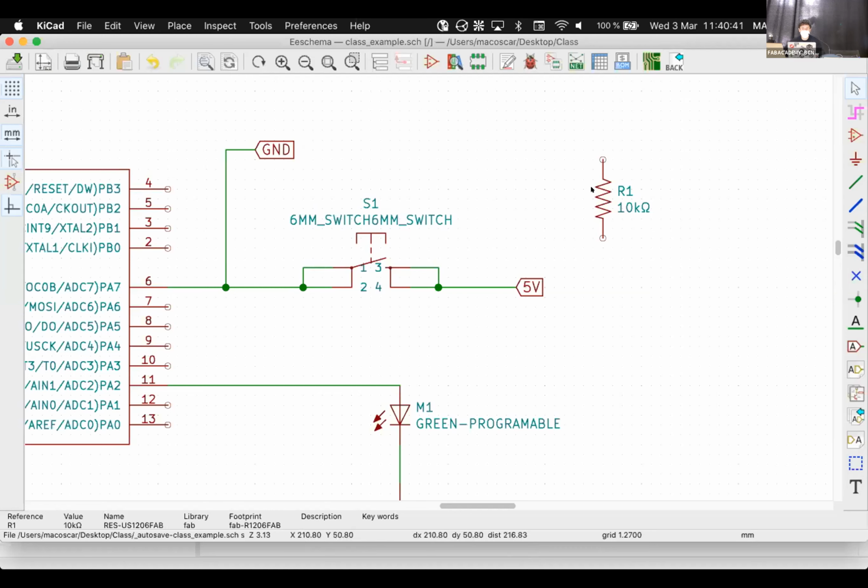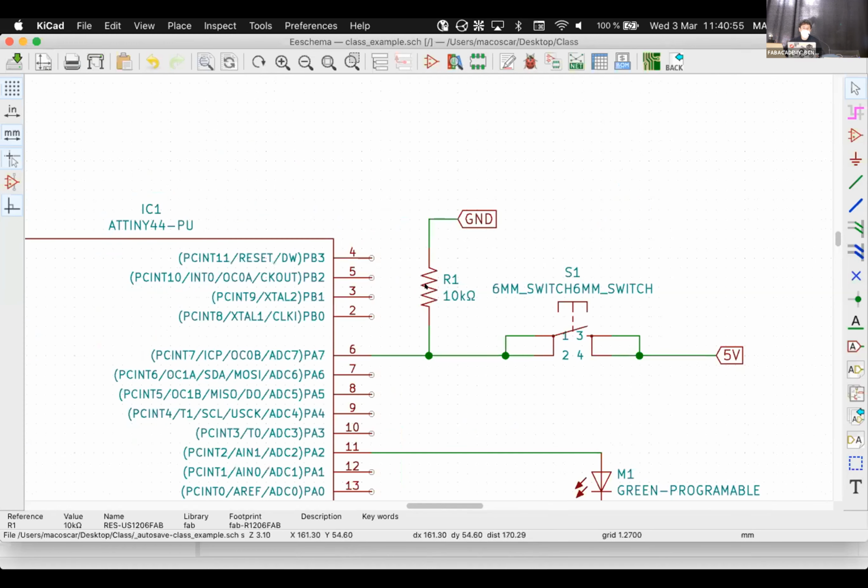So that's why we put the resistor in the middle, so that it limits the current that goes directly from 5 to ground. Yes, it's a short, but we have a resistor there. And okay, we're wasting some energy into the atmosphere by heating up a resistor, but at least we don't have a short and we don't burn our electronics. Yeah? Okay, but it's not right? It's a necessary evil, let's say. It's not right that you're going to have a short here with this.